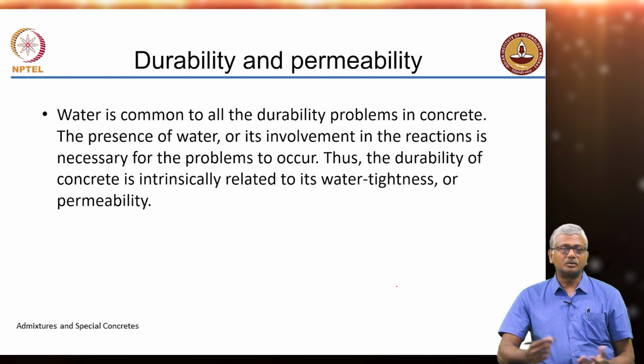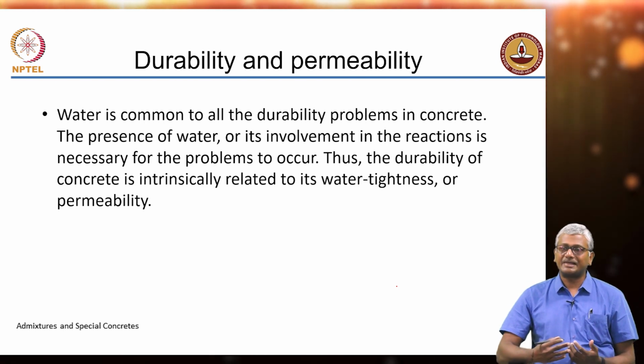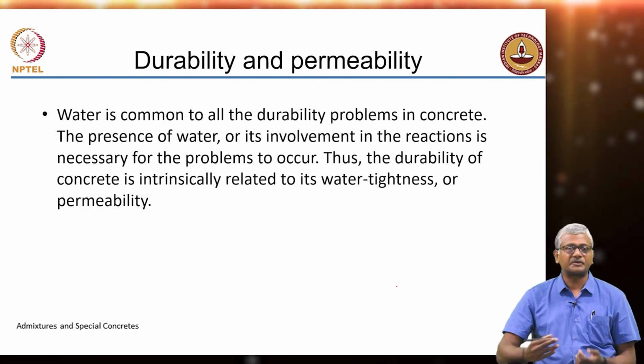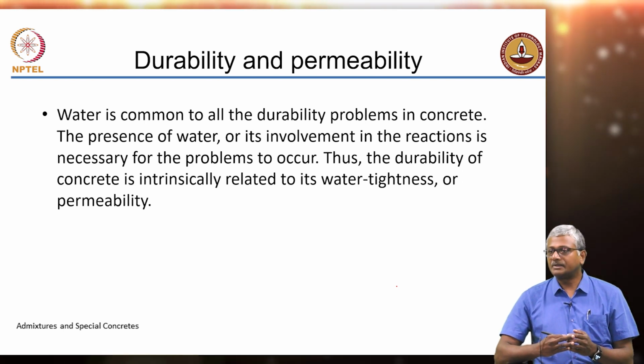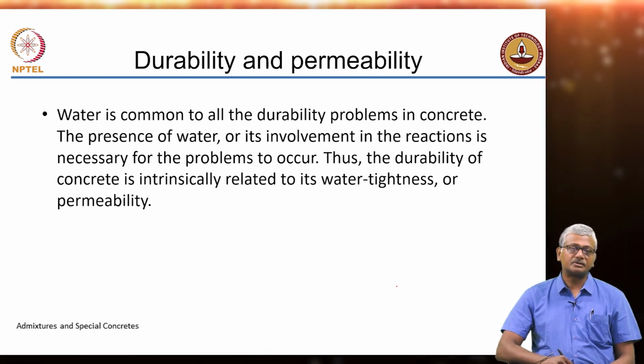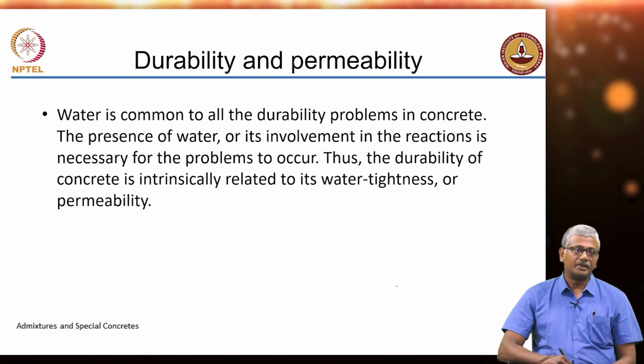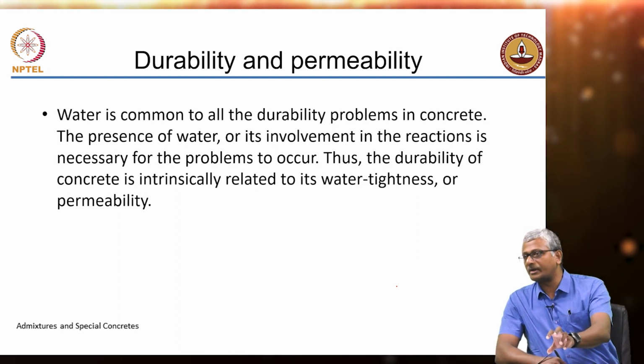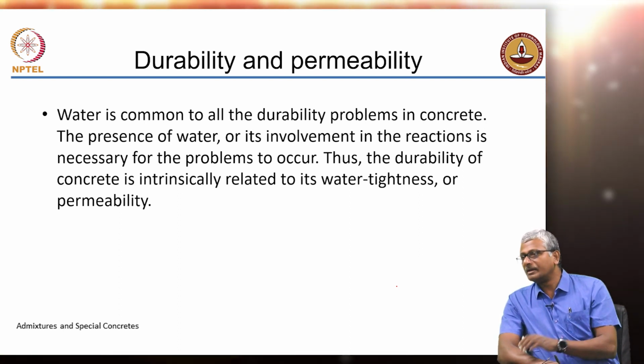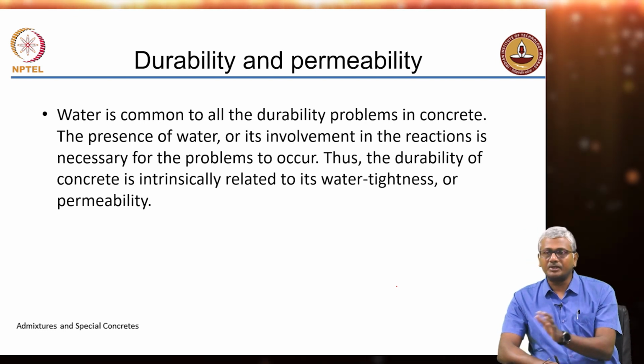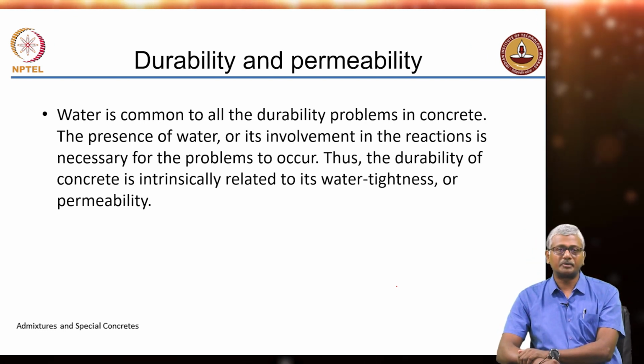Okay. We do not usually test the actual performance in different environments because each test may take several months to some years to actually perform. So, because of this we define the concrete quality in terms of its impermeability measured by different means, and we use that as an estimate of concrete durability.